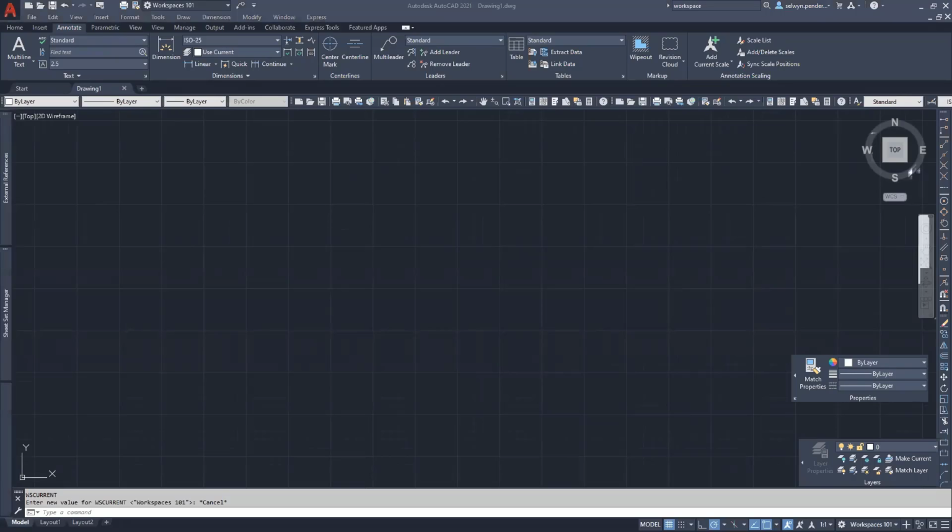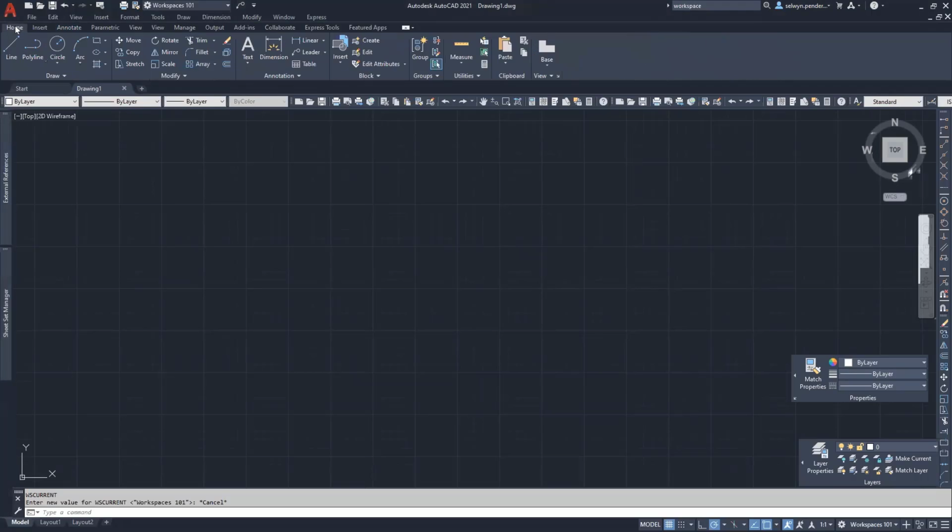For those of you that do use Civil 3D, that quick access toolbar can be a really convenient way of accessing certain tools that you maybe have to go through either a toolbar, a menu pull down, or even the ribbon. Maybe you've got to flick across a couple of tabs, then click on a panel, click on a pull down. So there could be 3 or 4 clicks to get to it. A popular one to put up there from my perspective is creating an alignment from a polyline, because it takes a few pull downs to get to. If you're creating alignments from polylines quite a lot, it can be a really useful one to have at the top.